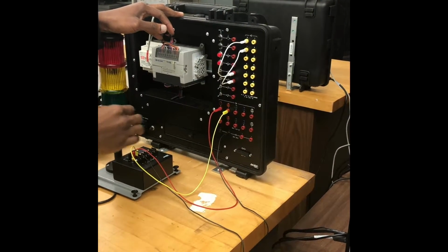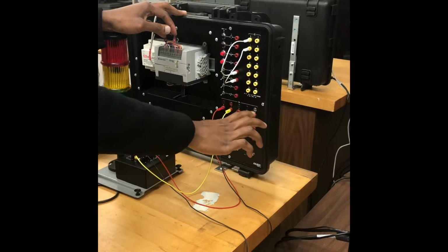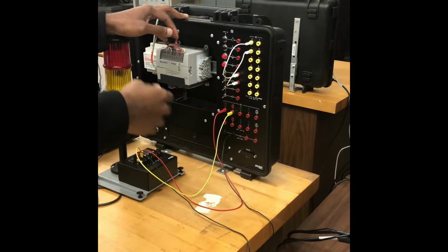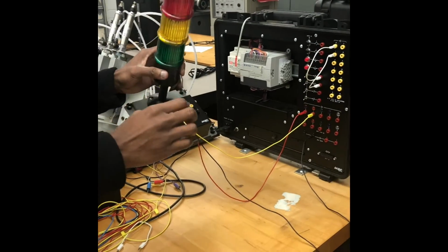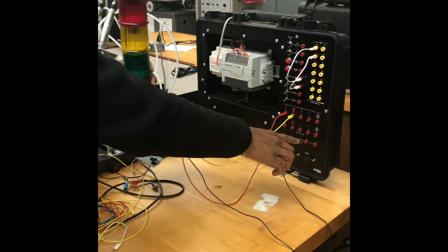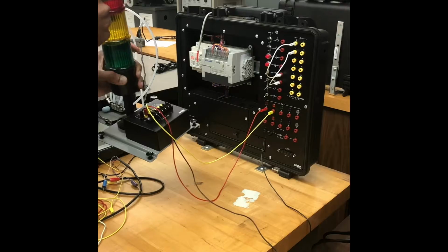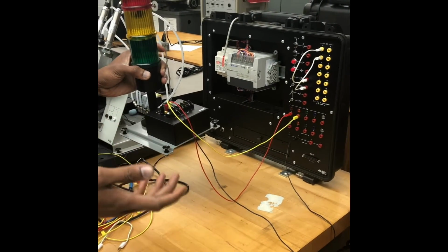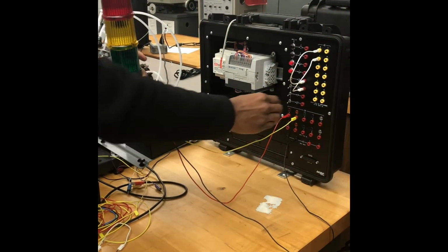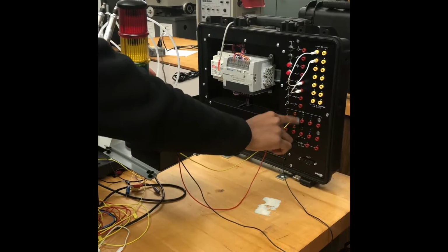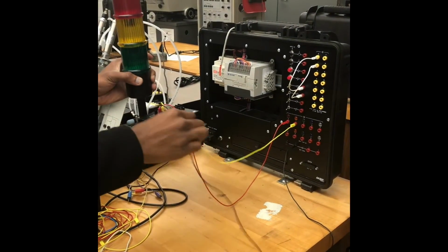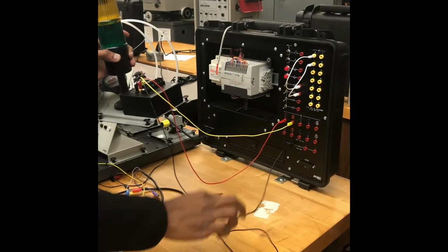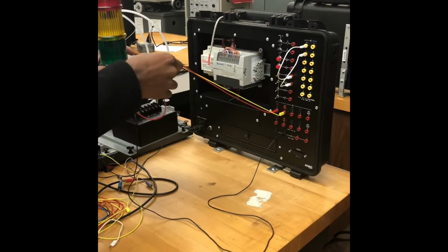And updating the outputs. Now again, these outputs are connected to the output port on the PLC. If you notice here, we have a light. Just like in our diagram, the 24 volts is coming from the output, going through the light and going to ground. This is what forms our circuit. So we have two circuits here. We have this one, 24 volts is coming, going through this wire, through the light bulb and then to ground. That's why we have a common ground. We have a common ground and we have our different outputs.